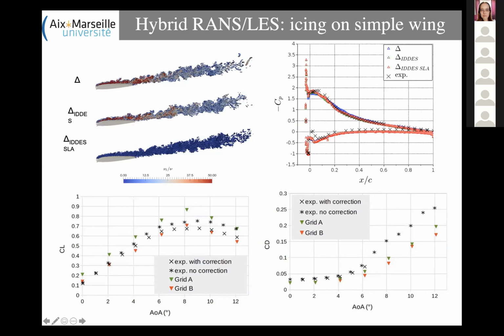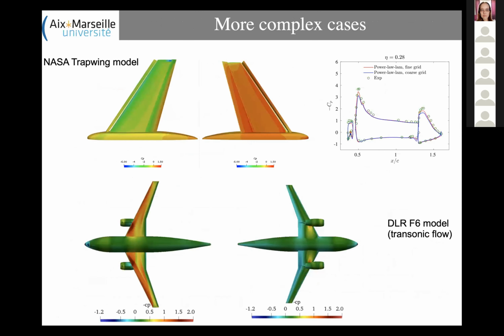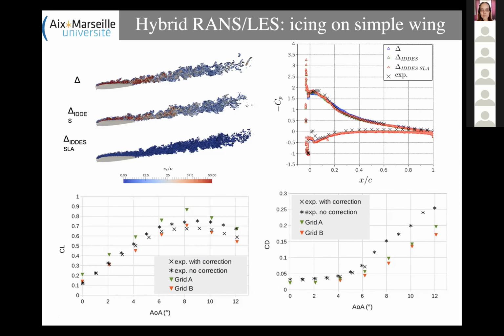Okay, here we have some problems if you look at the pressure side. It comes from the fact that it's good here, it's not good here, because there is a recirculation bubble here, which is fully three-dimensional. And in experimental data, they didn't average over the span-wise direction. So this is single location data, while in our case, we can run things like that, meaning averages.